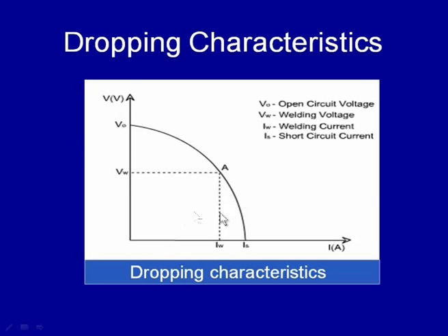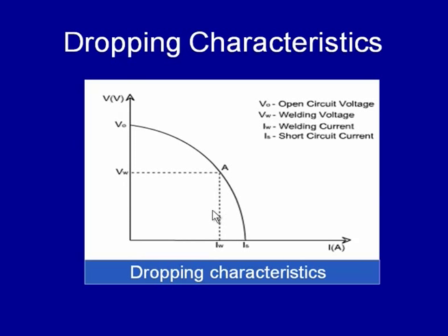the large change in the voltage. Indirectly we say that if we change the arc length significantly, the change in voltage will occur, but it will not cause much change in the welding current. So, the current will remain largely constant, and the variation will be very small. This is good for generation of heat at a uniform rate, and there will not be much fluctuation in the heat generation, so that a uniform weld joint can be obtained.